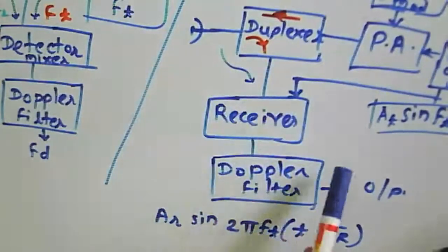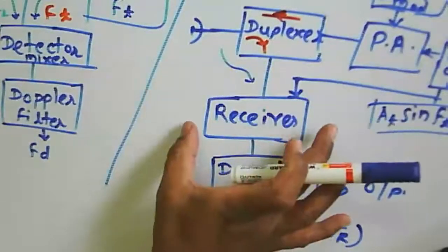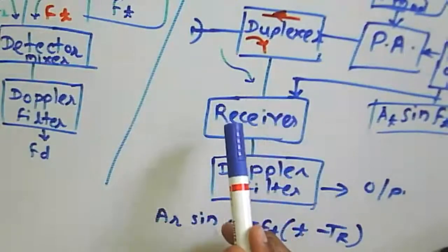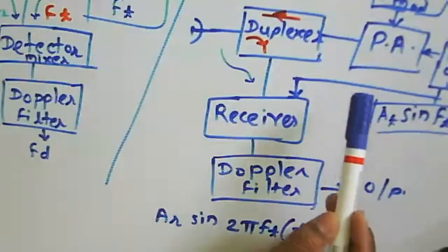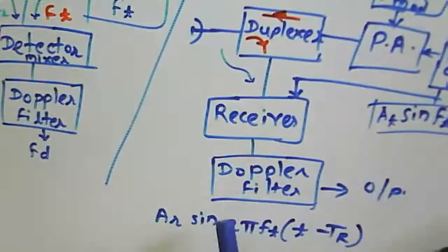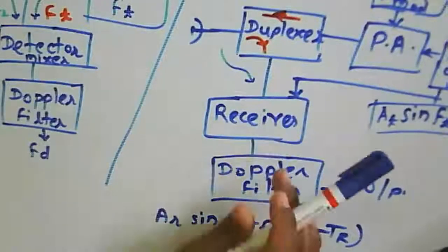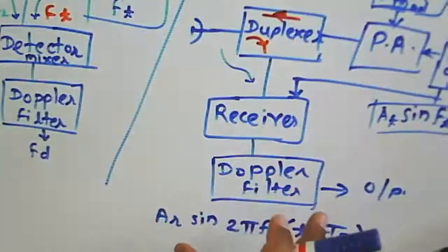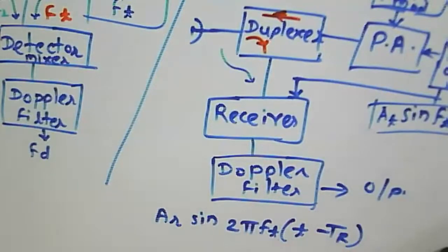Now this particular action, we consider that here, it is called what? The heterodyne one, because we are using a mixer here, and then we provide a local oscillator signal, which is nothing but a reference signal from the CW oscillator, and this is the mixer stage. So this action is called heterodyne. If we were using one more mixer, in that case we would say it is a super heterodyne structure. It has only a single mixer, so that's why we say it is a heterodyne.